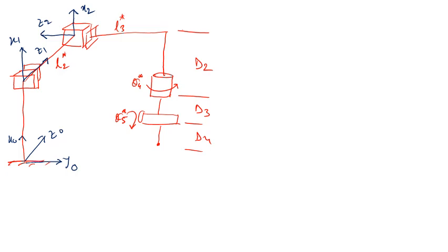In our tutorial video there was another prismatic joint, but here there is no prismatic joint. But to make life simpler, I assume another frame here, though there is no joint, but there is a bend, so I can assume another frame. So I put here Z3, and X3 should be perpendicular to both Z2 and Z3. So this is X3, and Z4 is the revolute joint.